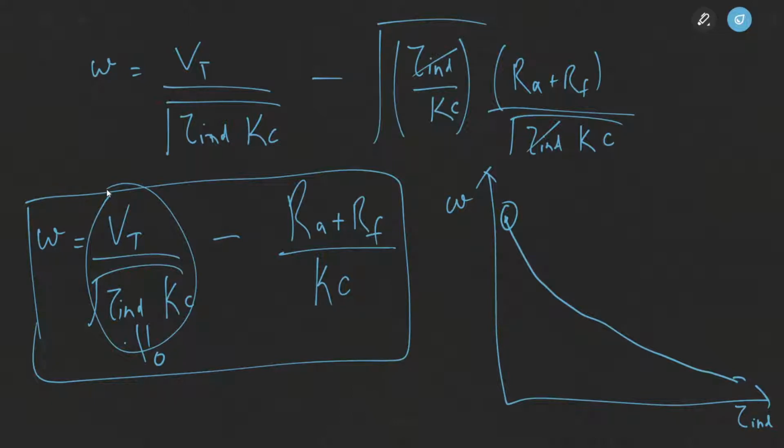completely. There is no sort of load attached to the DC series motor. It's freely running. In that case, the induced torque will be 0. Since the load torque is 0, naturally the system will balance out, and the torque induced will also be equal to 0.